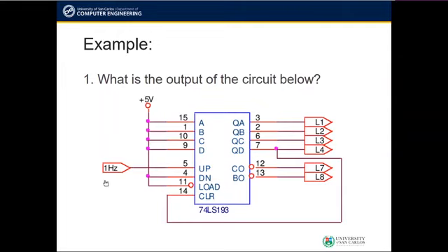So now let's discuss the circuit operation. Again, the circuit counts from 0 to 7 and then repeats. The parallel inputs here have no effects because the load input is supplied with 1. The clock generator connected to the up input and the DN pin connected to high will cause this counter to count up.